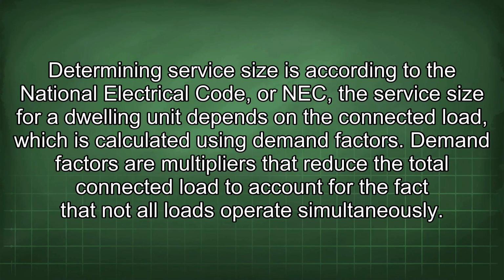Determining service size is done according to the National Electrical Code, or NEC. The service size for a dwelling unit depends on the connected load, which is calculated using demand factors. Demand factors are multipliers that reduce the total connected load to account for the fact that not all loads operate